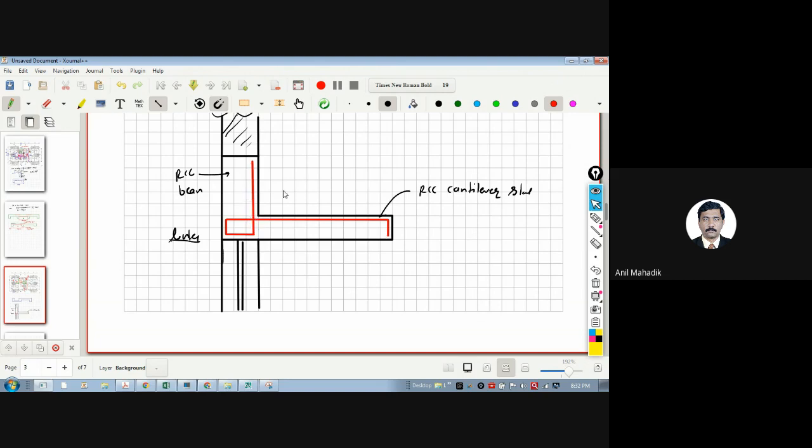Yes. So the bar is in one piece. Please keep in mind, the bar is like this. One piece only. There is no cut bar. This total bar is one piece. And this crossing is required to avoid the cracks. So when there is a change in the angle between the two members or the same member, some beam and slab angle is changing, for cantilever slabs, or there is a staircase, or there is some inclined slab or whatever, please keep in mind, you must provide such kind of crossing. Otherwise, there will be crack here.